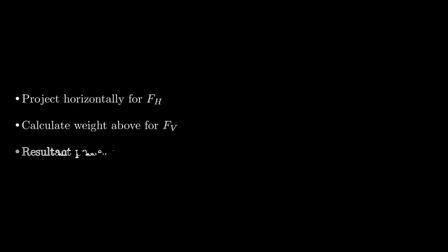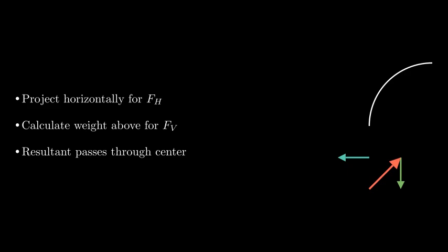To solve any curved surface, project it horizontally for Fh, calculate the weight above it for Fv, and remember that for circles, all paths lead to the center.